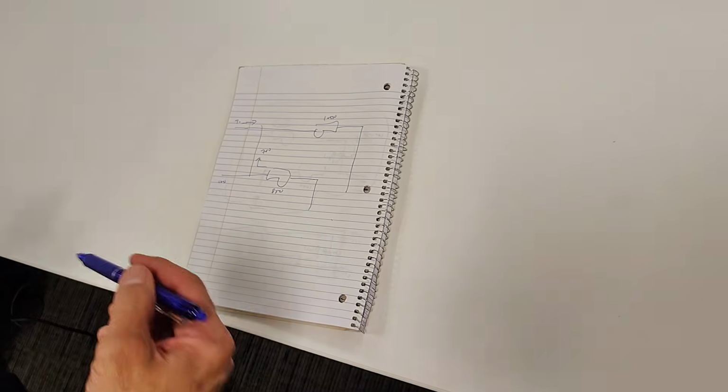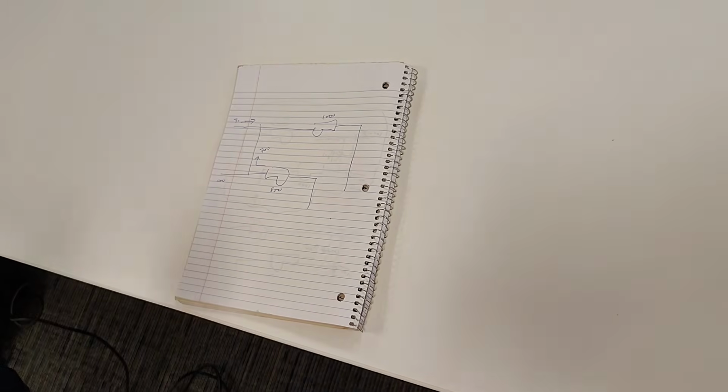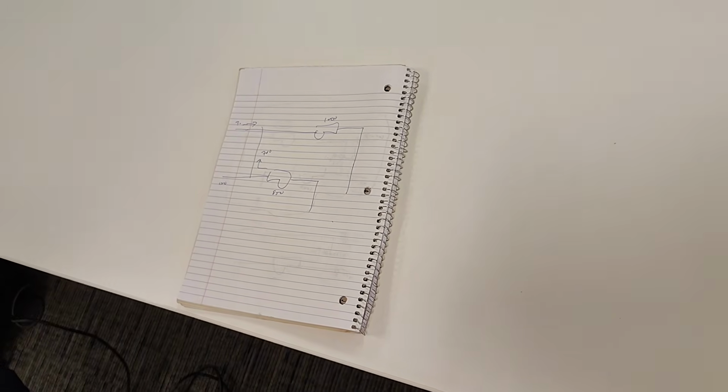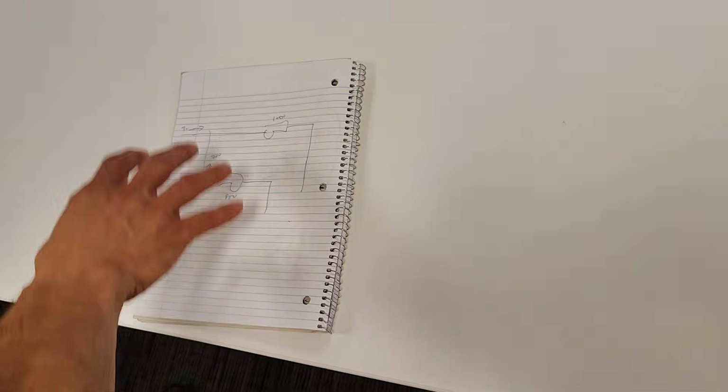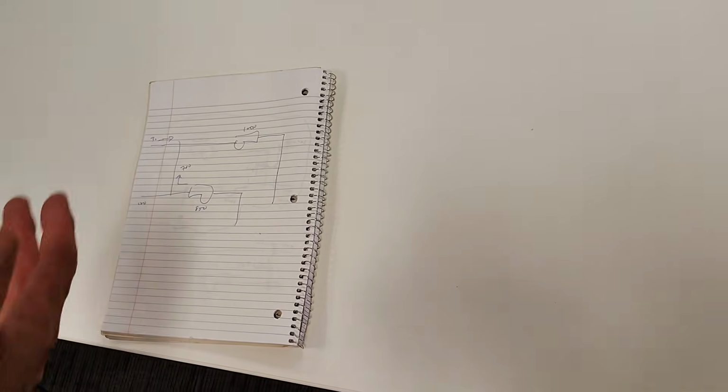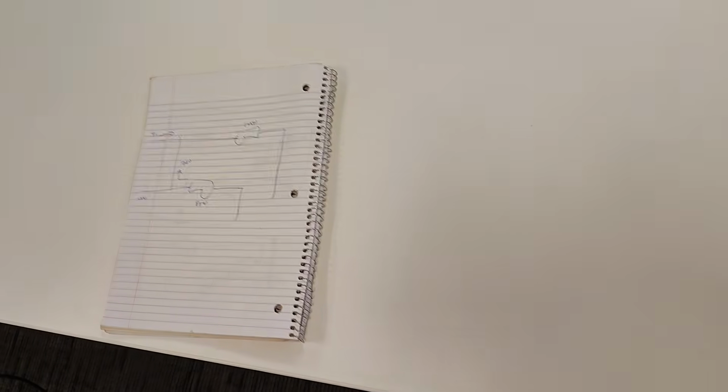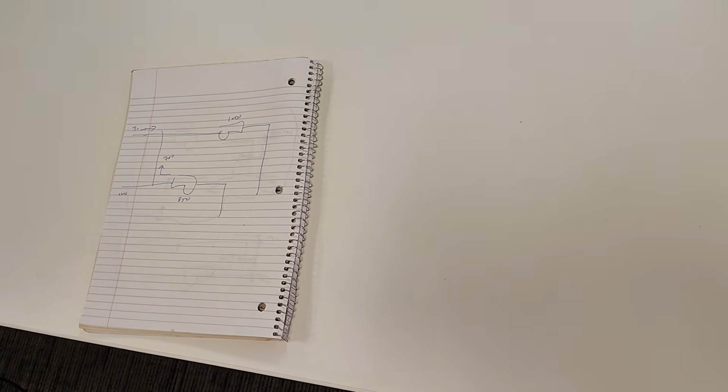Now, when you set all this stuff up, you set it up with pressure gauges, and you measure and you make sure that you've got it, and then he programs in minimum position. And minimum position gives you this. Beyond minimum position is, hey, the outside air is cold, and I want cold in here. So let me get that for free. And that's when we start seeing these things open up more, these things close.